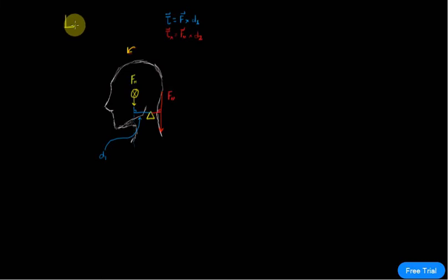Now remember that our convention is set up this way: anything along the y-axis going upwards, anything on the x-axis going to the right, and anything causing an anti-clockwise rotation is denoted with a positive sign. So in this case, the torque of the head is equal to the force causing that rotation, which is the center of gravity, multiplied by that perpendicular distance, which we said was D1, and that's going to be ascribed a positive value.